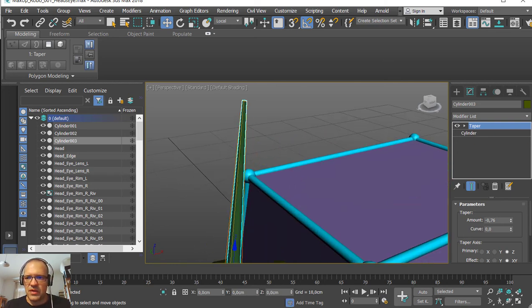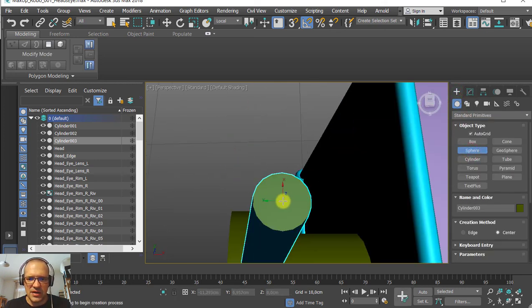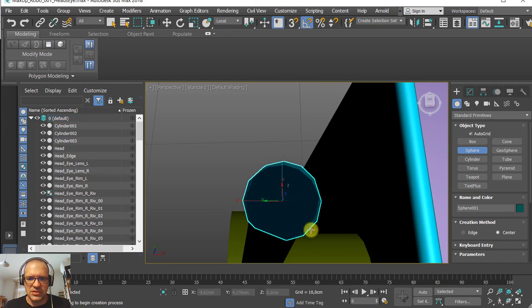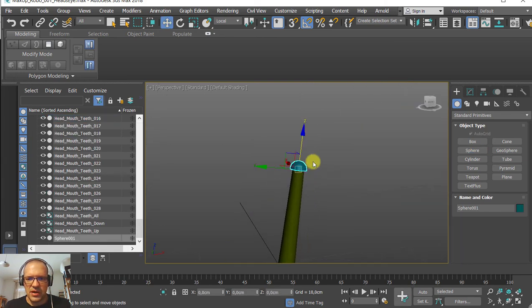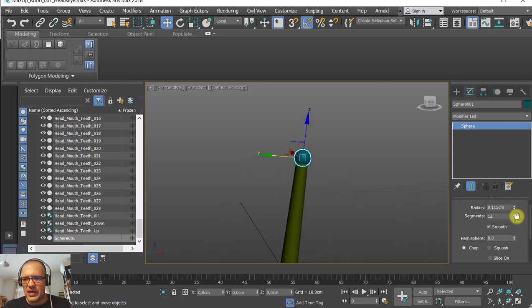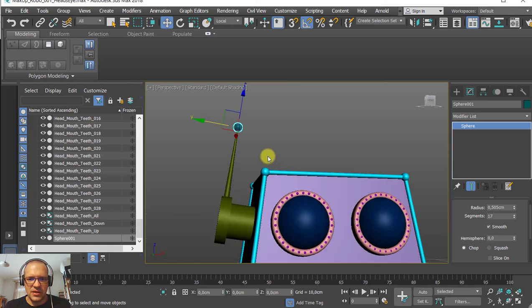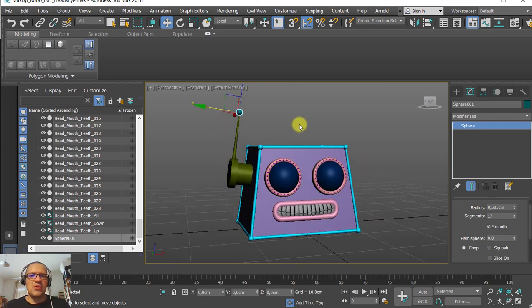Okay, cool. Now let's go up here and try to add a cylinder on top of it. Not cylinder, sphere, sorry. So I'm zooming in, trying to pick the right location. And here we go. Because it remembers my previous settings, it has this hemisphere function. So let me just zero it out. Right click on the value and choose an increased radius, and maybe the segments compared to the whole should be enlarged. Okay, so have a good time, practice a lot.